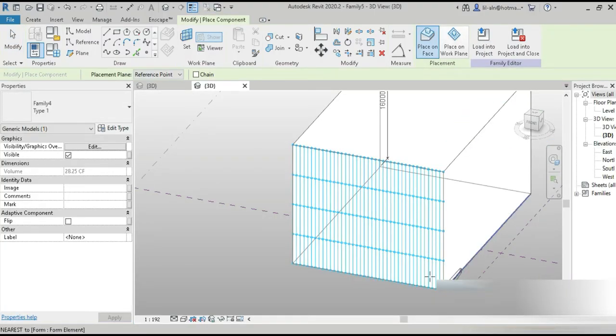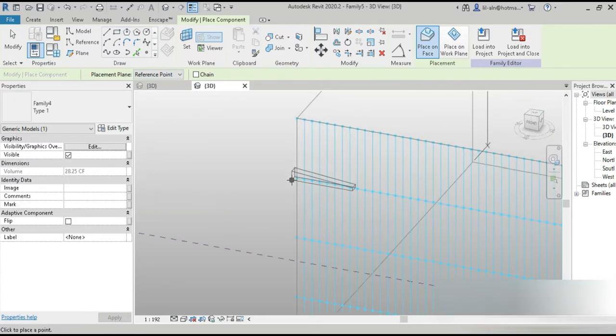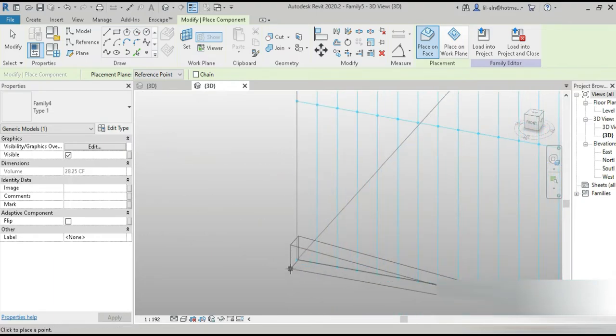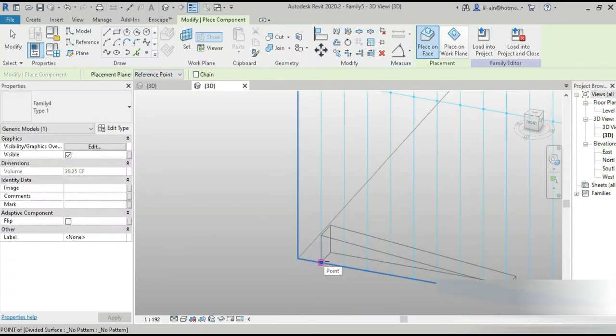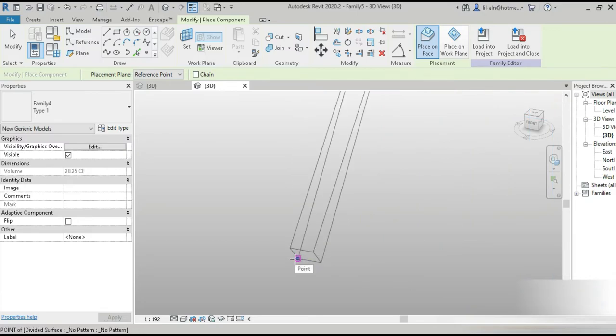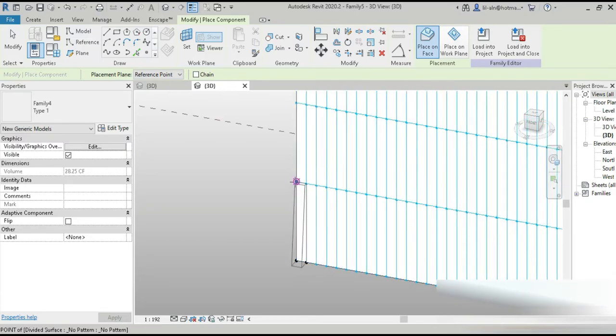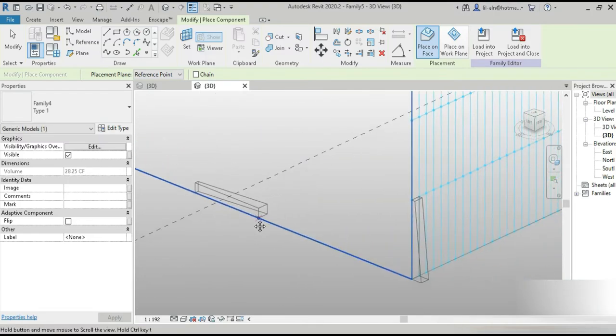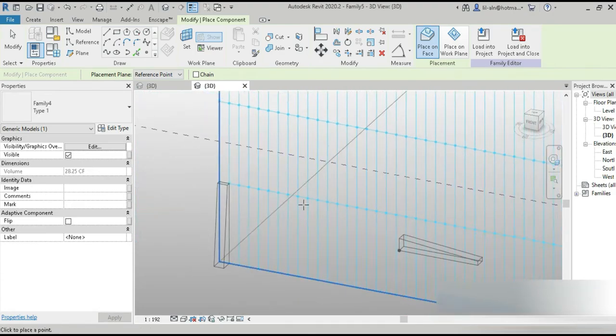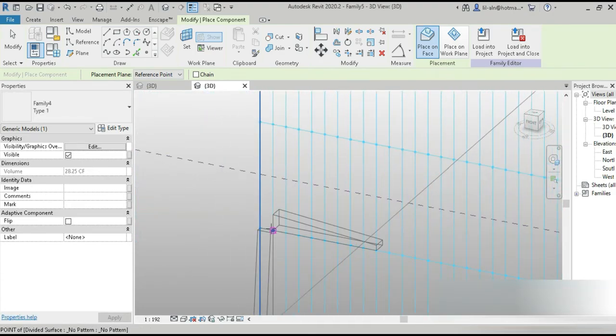So it automatically got loaded into the project, and these are the control nodes that we activated. And this 1, 2, and 3 and 4 are the adaptive points. If you remember in our adaptive family, the 1, 2, 3, 4 that we had set. So this is how we are going to replicate our facade in this. Let's start pasting. So 1 and 2, okay, and 3 and 4. Here you go. Extremely easy, nothing hard. So you know what, okay, this is done.